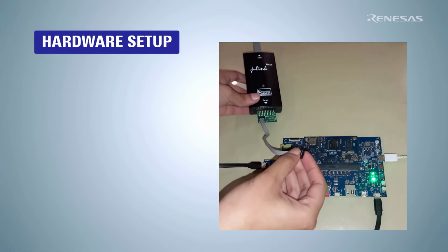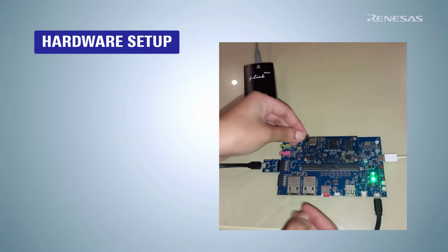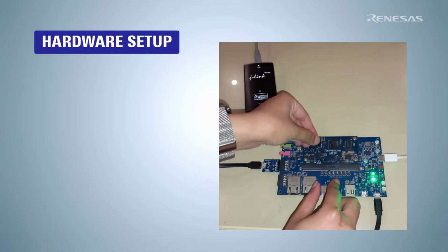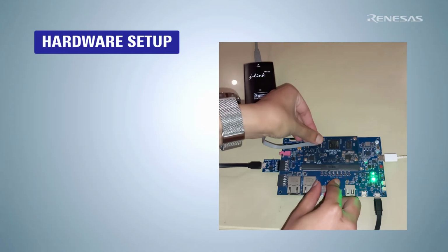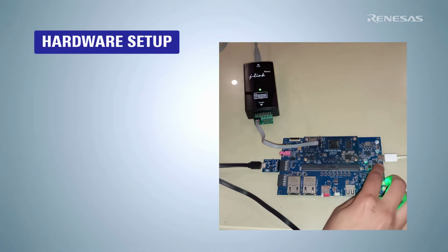We will connect this connector cable to the debug port, which is CN2 on the SOM module, and connect the other side of the J-Link debugger to your PC. It will then power on. With the hardware setup complete, power on the board.